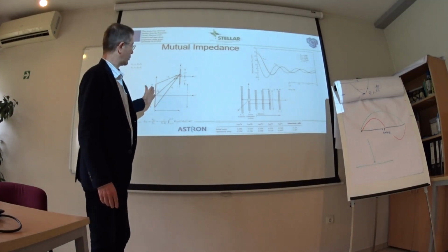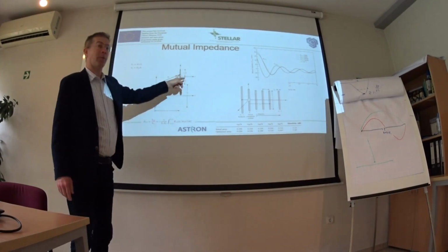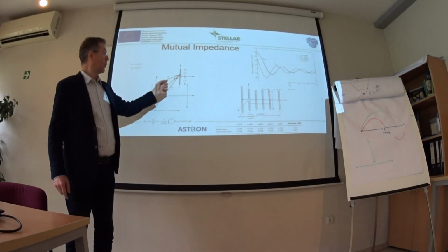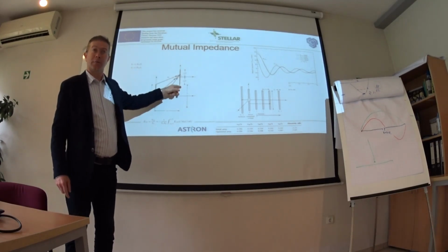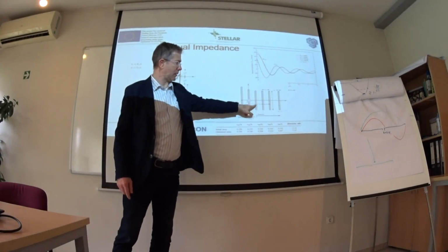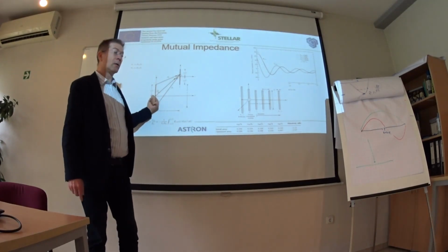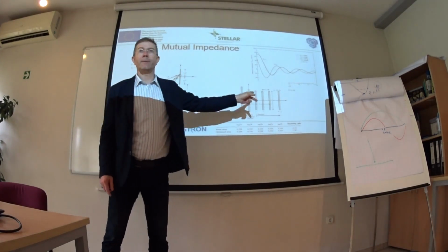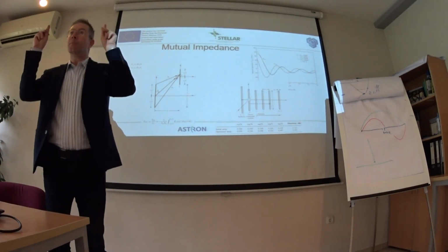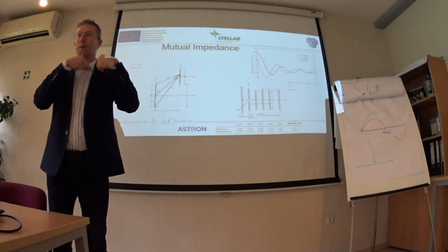So this picture tells us we have two elements, here and here, and they will be electromagnetically coupled. The currents flowing in the parasitic element, the director in this case, will induce currents into the driving element. And the driving element will see an impedance that is imported from the adjacent element.